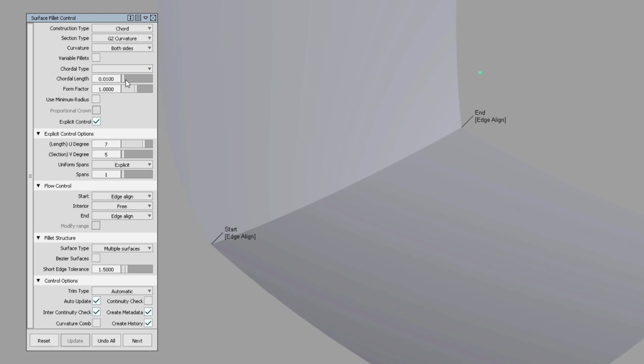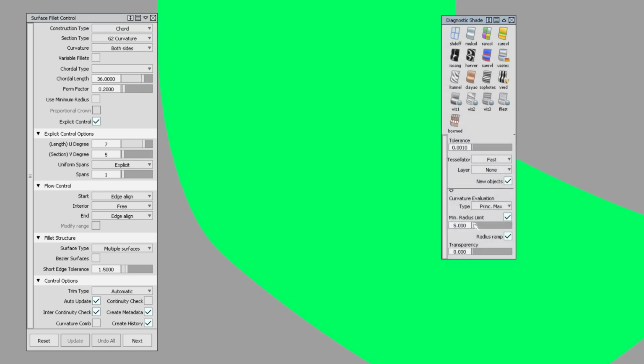From a design perspective, fillets are needed to smooth out sharp edges. Their exact size and shape is always very important to the designer. From an engineering viewpoint, the minimum radius is a particularly important factor, both in terms of pedestrian or occupant safety and feasibility issues such as metal forming limitations.